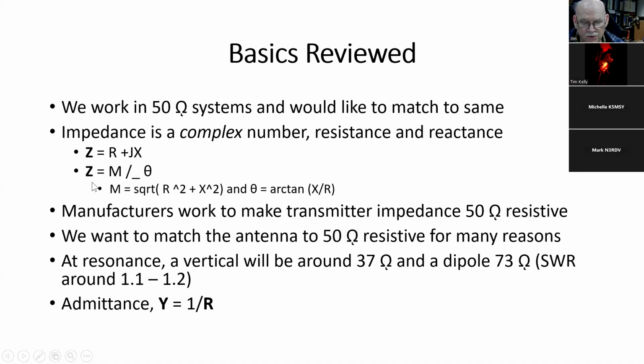Another way to express impedance is a magnitude at some angle. The magnitude is the square root of the resistance squared plus the reactance squared, and the angle is the arctangent of reactance over resistance.